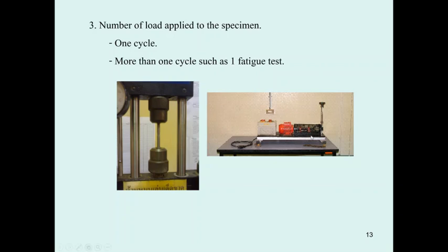So when the specimen, which has very small micro cracks, has tension, compression, the crack is going to open, close, open, close, open, close. When it's repeated many times, the material will fail by fatigue of the material itself.